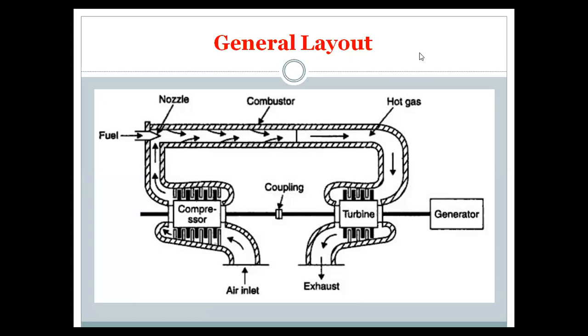This gas turbine power plant consists of a compressor, then combustor, then turbine, and auxiliary equipment such as starting device, lubrication pump, fuel system, fuel injector, or we can call it a nozzle, oil system, duct system, etc. And maybe a modified plant, we require a modified plant to improve the thermal efficiency of our gas turbine plant.